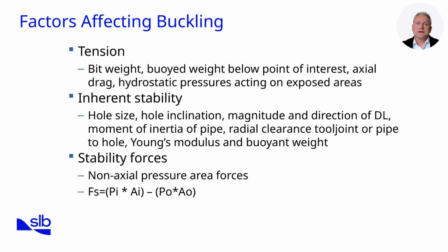Finally, we have stability forces. These are non-axial pressure area forces caused by pressure differences acting across the pipe. The net force is expressed as internal pressure times internal area minus external pressure times external area. Depending on the balance, these forces can either help resist buckling or increase the risk of instability.